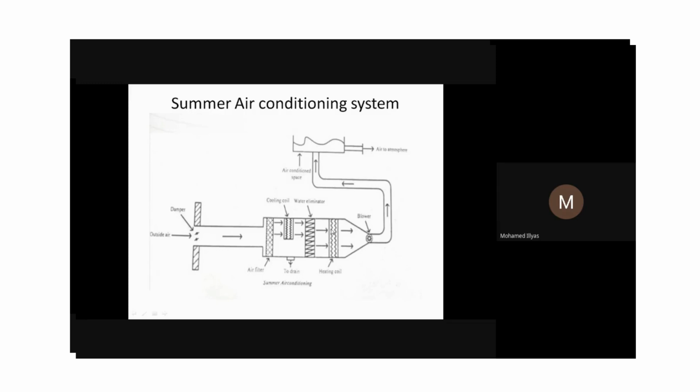Okay, so we have to cool the air from the superheated state to the saturated state, because of cooling. Once the temperature is reduced well below the designed temperature, in the saturated state, we can heat it further to achieve the required temperature. For example, if the required temperature we have set is around 20 degrees Celsius, that's why the temperature is decreasing here. After that, phase change is taking place. In that region, the temperature remains constant.